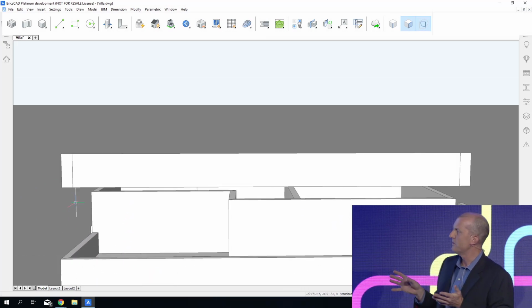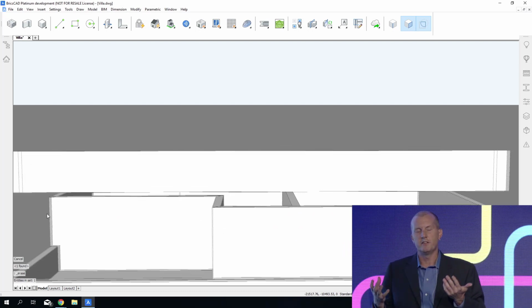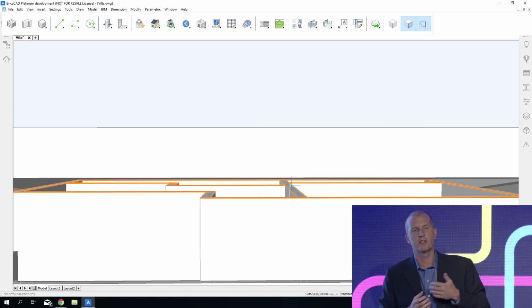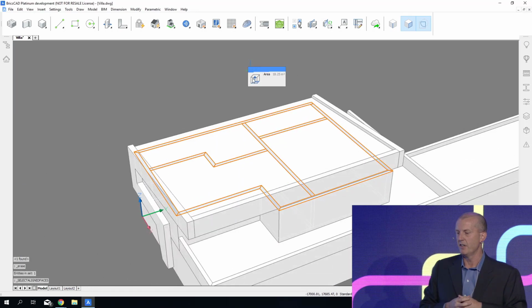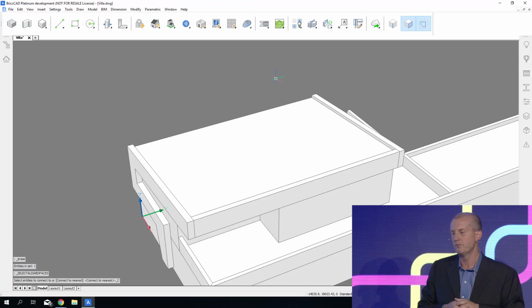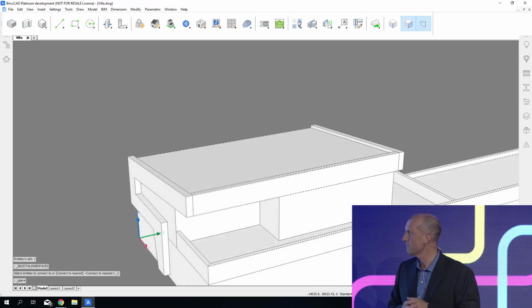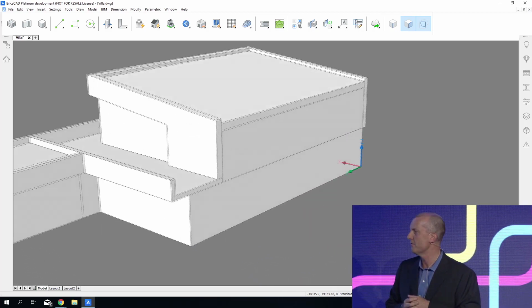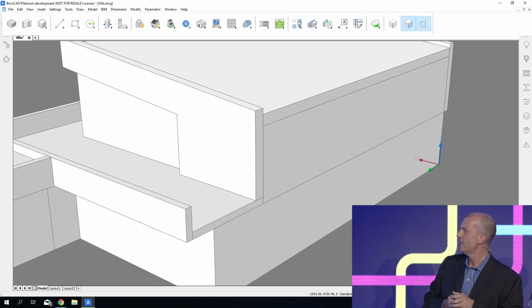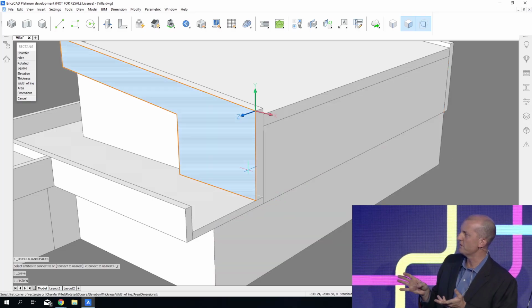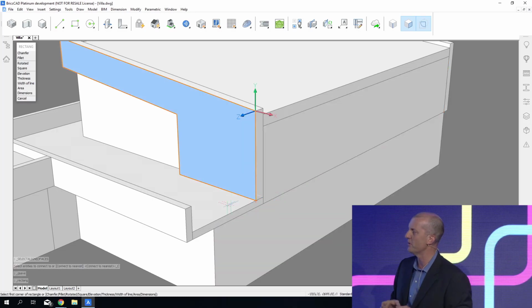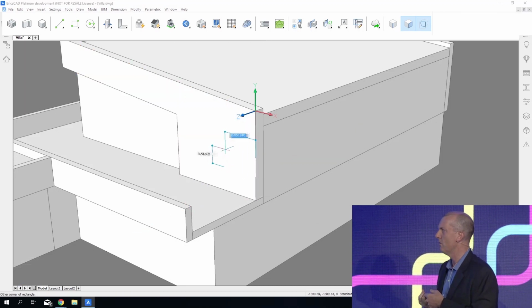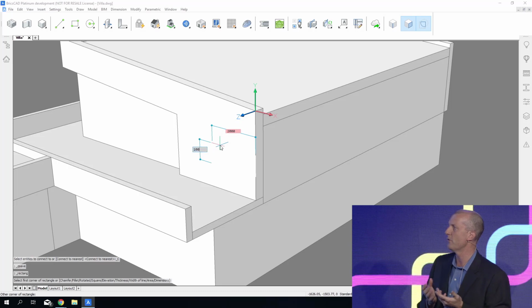So now our walls didn't come with that move, but we can easily connect them to it by just selecting aligned surfaces and then attaching them to the roof. So very quickly, we're starting to bring this design together. One of the other things we can do is to align with the band that's on the front of the parapet. We can select that point as a reference point, carry it back to the wall, and then draw a rectangle to create a void.